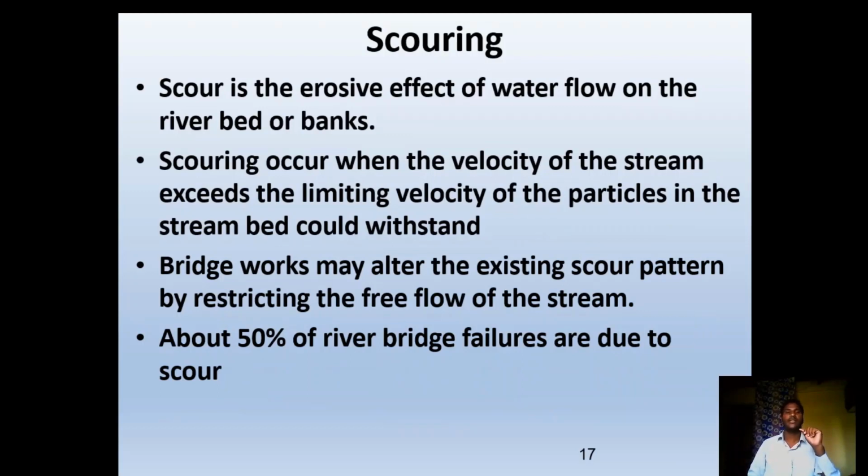Scour is the erosive effect of water flow on the riverbed or bank. Scouring occurs when the velocity of the stream exceeds the limiting velocity that the particles in the stream bed could withstand. Bridge works may alter the existing scour pattern by restricting the free flow of the stream.